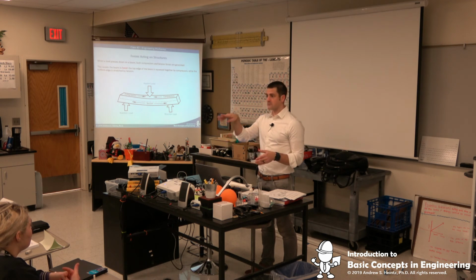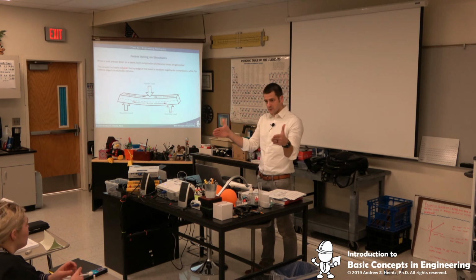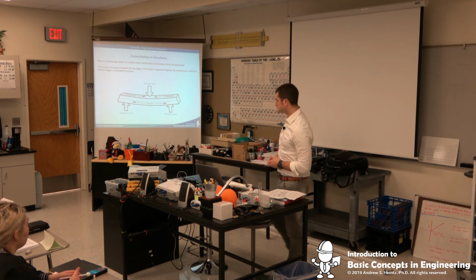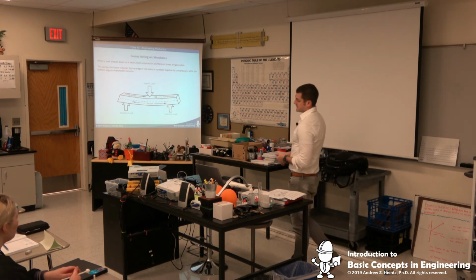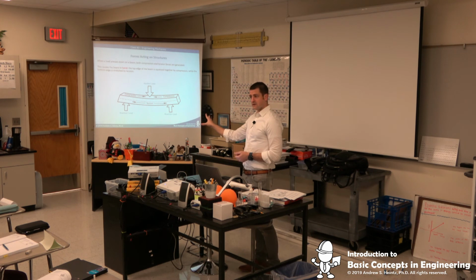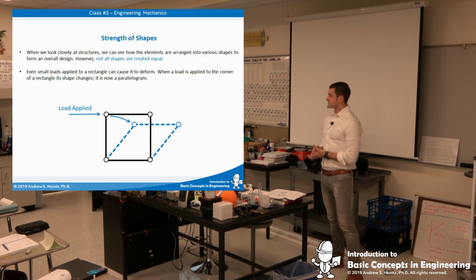That's why sidewalks have built-in cracks every 3 or so feet, to allow for expansion. Because if you don't provide any spot for it, the concrete will expand and it'll crack. Or it'll contract too much in the winter and it'll crack. Okay? Does that all make sense? We've all got that down? So bending is a combination of compression and what? Tension. Good.